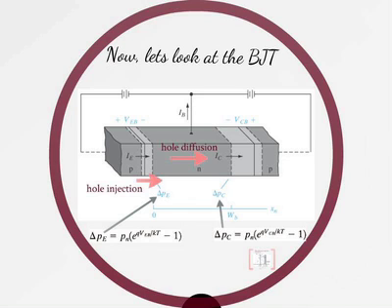So go back and think about just the forward bias PN junction that we had, where we assumed a long side, right? We assumed that was pretty long. Then you just had this thing going to zero eventually, at infinity. But now you have a new boundary condition because it's not long, you have another junction there. So you apply it. The solution is pretty much the same. I mean, you get an extra term, but it looks pretty much the same.